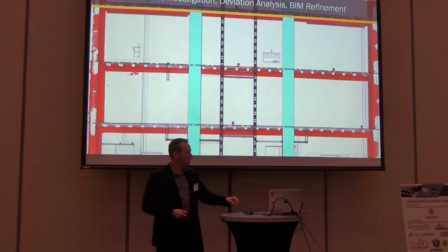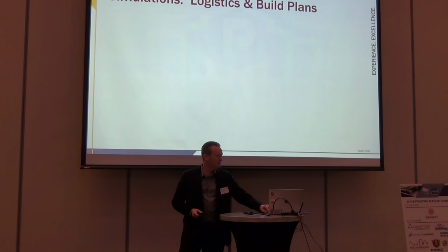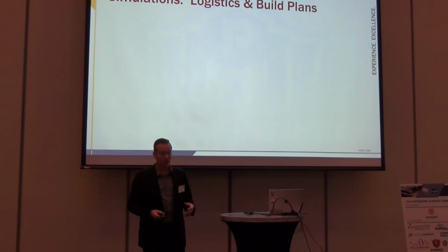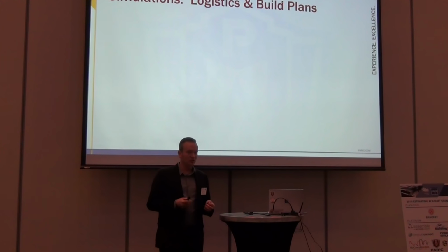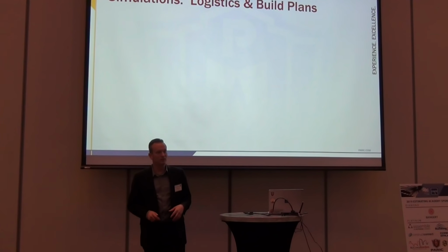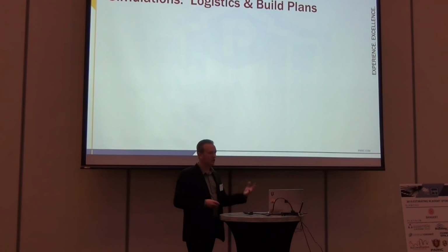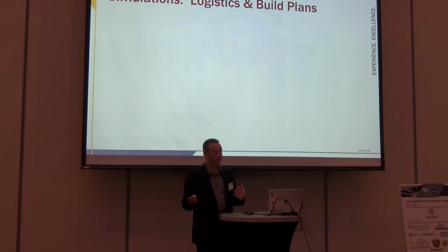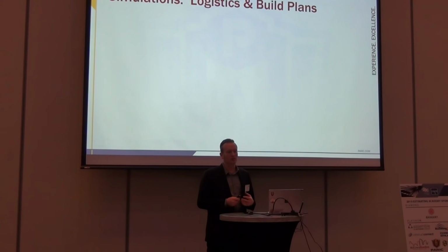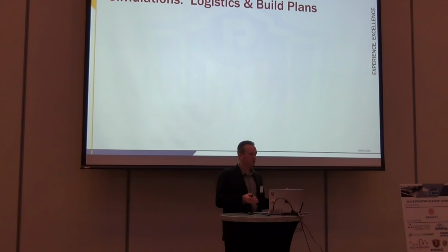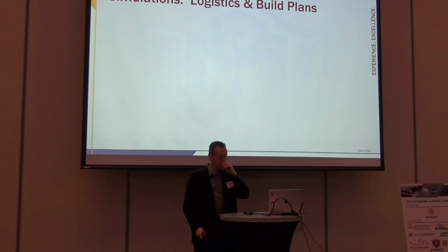Well, there's a lot going on in these buildings, so I'm going to stop this and go back so I can explain what's going on here. When you go into estimating, or trying to plan or design work, you need to understand the environment that you're building in. Whether it's a building or a greenfield site or a brownfield site, you want to know what's going on under the ground, above the ground, next to you, who my neighbors are, what roads I'm going to be using, can I carry heavy concrete beams down the middle of this road, or am I going to get problems with that? All these different things go into how I'm going to plan a job, bid the job, and schedule the job, right?